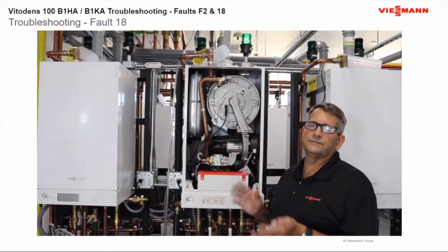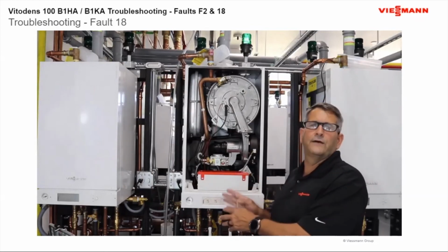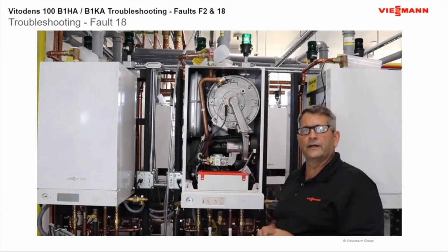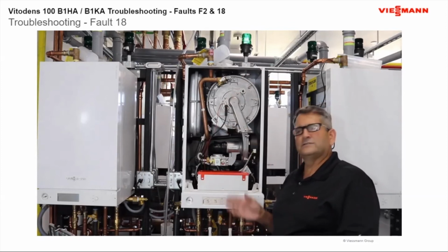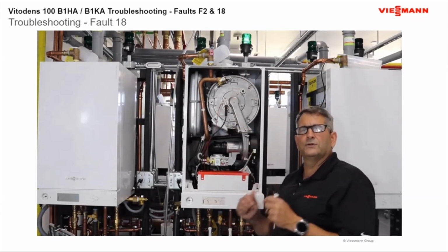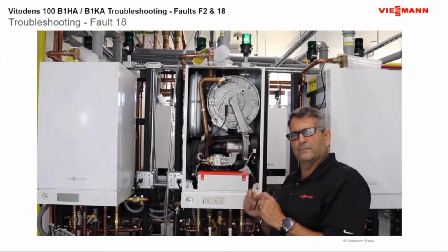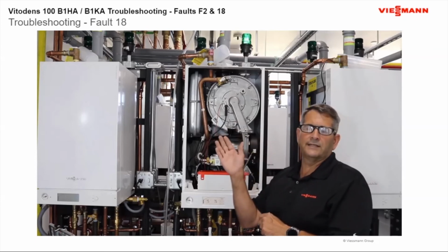As you can see, it was a little easier because I do have the outdoor sensor here. Sometimes we have it 8 to 10 feet off the ground on the outside, and we're going to check that. But I always start with pulling my wires off here to make sure that I do a continuity check or a quick test to make sure that my wires are not broken, because I'm going to go outside and test that anyway.